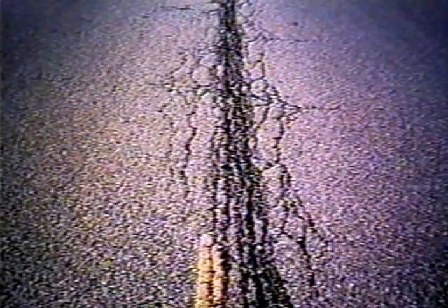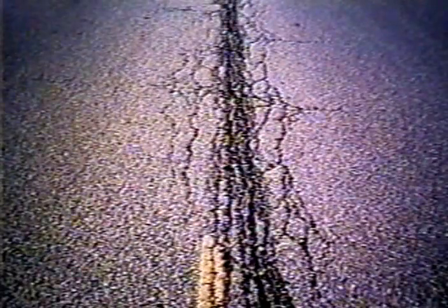Now, if we look more carefully at this pavement, the rest of it looks pretty good. You've got real extensive raveling just in one concentrated area right along that longitudinal joint. Frankly, that's not that uncommon because it can be difficult during the construction process to get good compaction. And if you remember, if you don't have good compaction, if you have air voids, that lets more water and air into the mix, it accelerates the oxidation and deterioration, and you have raveling occurring before the rest of the pavement.